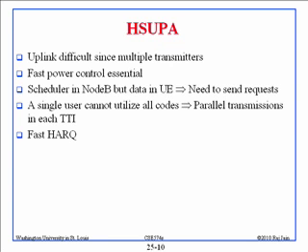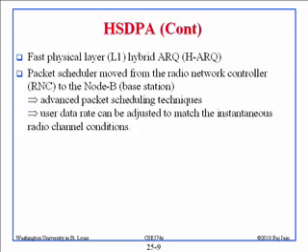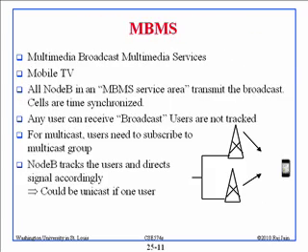Right? Here, now we have to distribute it. And then HARQ has to be, again, same thing, we have to implement HARQ if we want to implement. By the way, it's just called fast HARQ, but basically it's the same thing. Now we have to make it more smart. This was not there before. So it's just HSUPA was done in some release, as we saw. That was release 6 in 2005. Right? And then they were combined together to form HSPA.